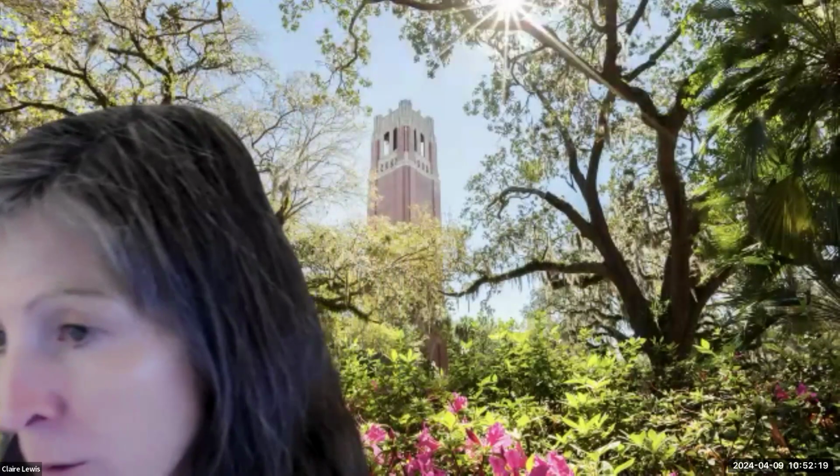I've tried to group some of these questions together, so I'm just going to go down the list that I have here. The first one I have is: is there a way to determine a city or neighborhood's impervious percentage? You can, yes. Many municipalities are moving towards having an inventory of impervious cover on the local GIS, Geographic Information System, website. That's often something that can be accessed publicly, so that's probably the best and most direct way to do it.